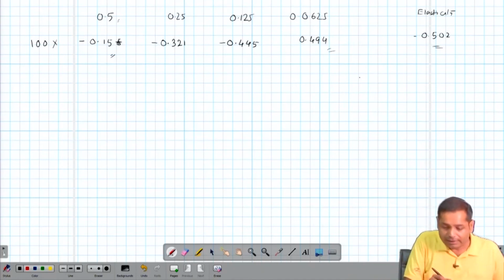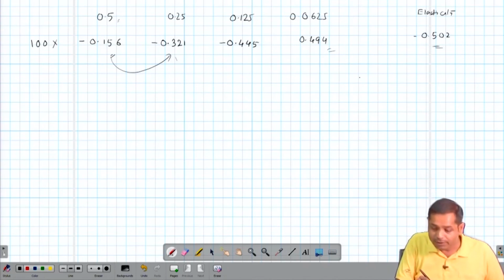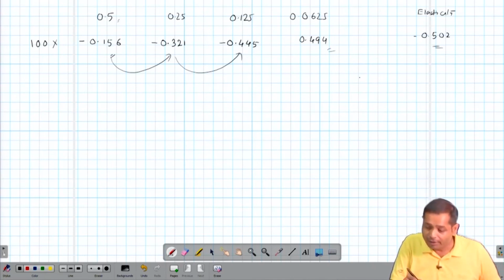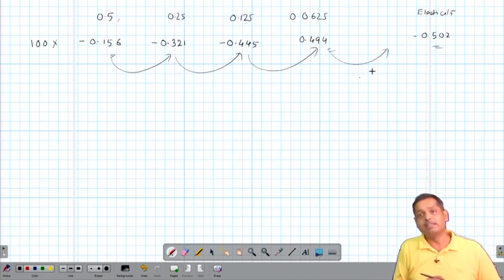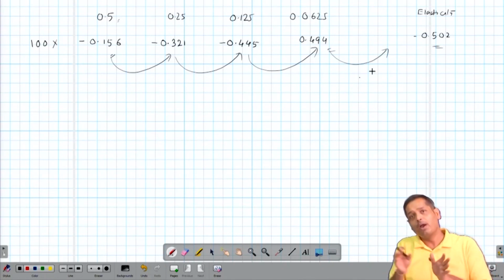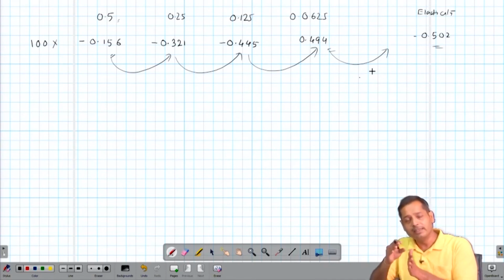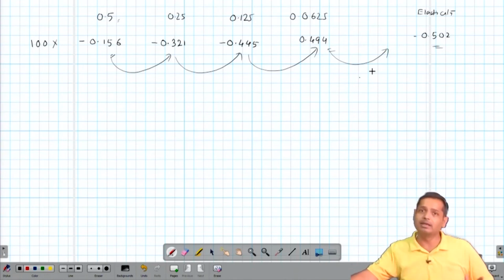For instance, from this to this, the change is significant, it is almost double, but then from this to this, the rate of change is now less. Now again from this to this, it is very small, and with one level of refinement, you will see that it will hardly have any change. So when you see that even after increasing the number of elements, the change in the solution is very small, within the tolerance level, we can assume that this is the converged result.